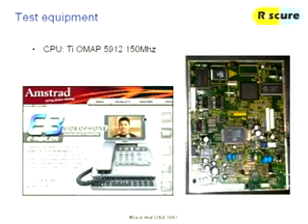So the start was that we first show what you can hear, if you just put something on that you can listen with. What it is, is a normal hand scanner that you can tune. And what we do is tune it to the clock frequency. So this is 150 megahertz. And then you just put it on AM or FM. As an antenna, we use a very simple loop antenna, which is a bit of coax, and then you just have the core in a loop, and that's it.